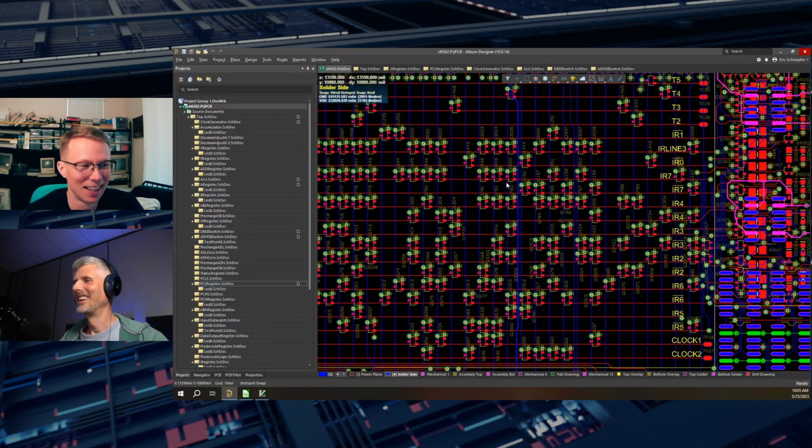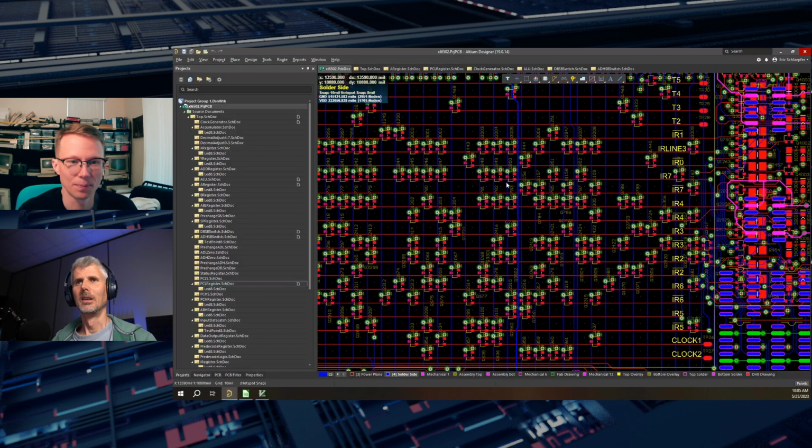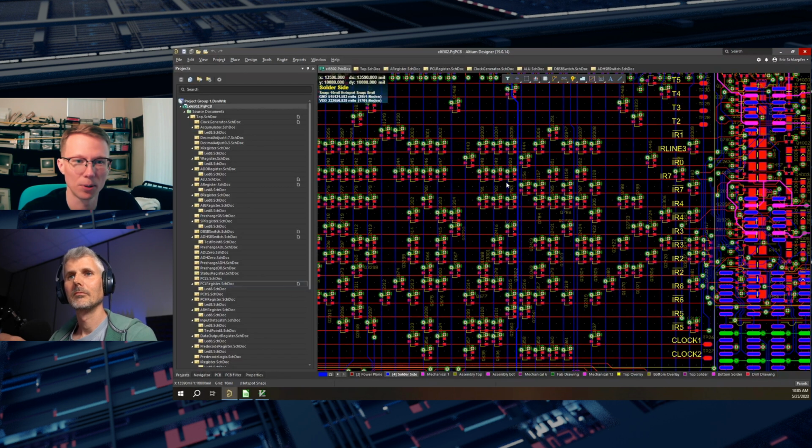Yeah. So okay, you got your assembled boards back then. So now you're on to this final stage of verification between the intention, right? Which you said you can check on the Visual 6502. Yeah, and the most important thing you've got in hand was coming up with a power-up strategy. In this case, I used a power supply with a current limit. I started with a rather low current limit, and I slowly brought it up.